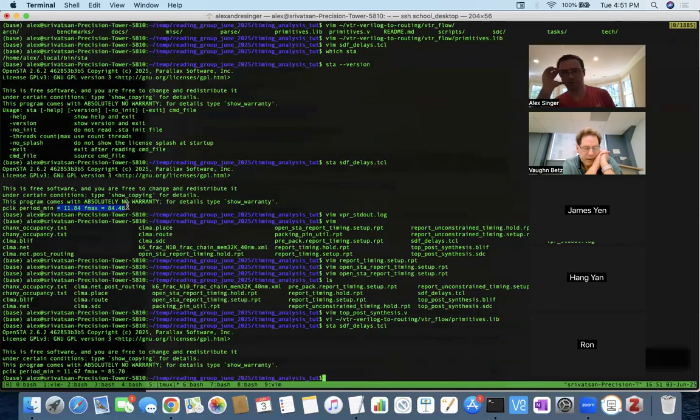Is that pessimistic or optimistic? Well, unateness helps you, right? Because you can be less pessimistic because you get to add up a bunch of rising edges and a whole bunch of falling edges, and then you only have to max them at the end. So if you have all unate logic, yeah, you can keep track of your rising and falling edges separately, keep adding them together, and then at the very end say which one is the max when I hit the register.